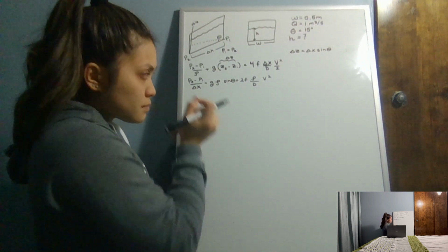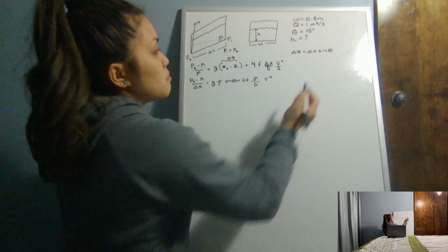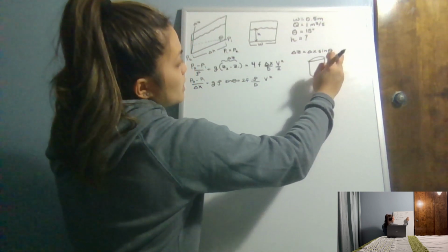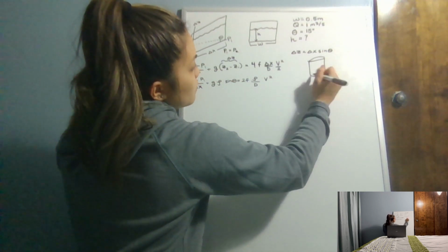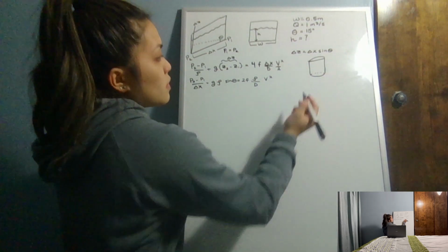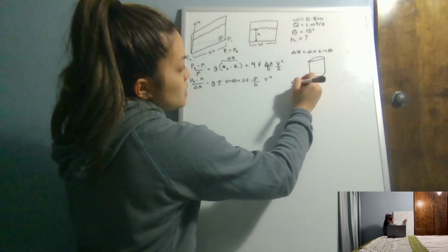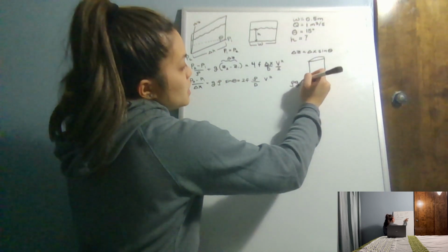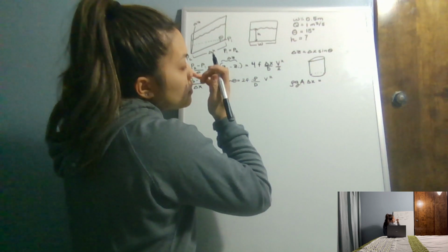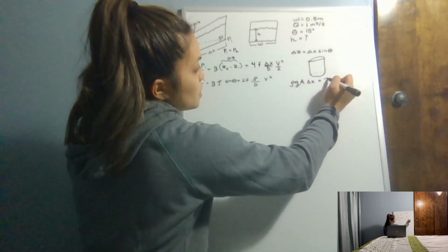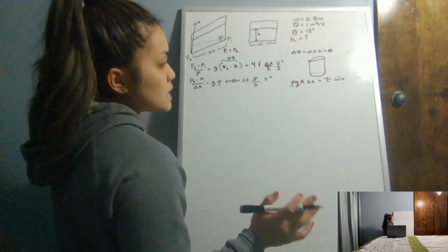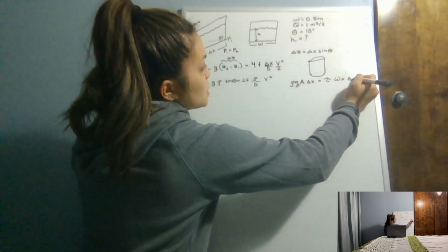What we'll need to do is model it by a circular pipe so that we can approximate the non-circular pipe. For a circular pipe, if we were to connect it to shear stress, we know that the density times the gravitational acceleration times the area times the change in position x can be equal to the shear stress times the wetted perimeter, which is the area on the sides, times the change in position x.